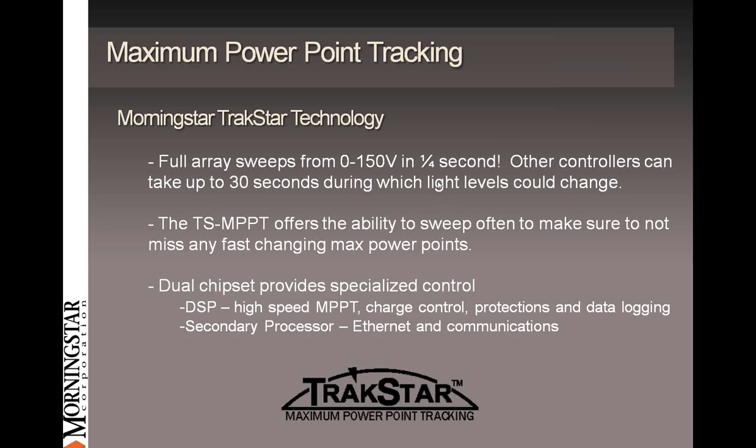And this is important. And again, the SunSaver MPPT generally tracks the whole array in a little less than a second. So very high speed in these applications. Other controllers, minimum of 30 seconds, sometimes more. They can get thrown off by effects from changes in the light. Even the battery voltage can cause some changes if the inverter has a large load or something. That can throw the whole system out of whack, during which sometimes the sweep has to start all over again. That's a big pain when it takes a minute.